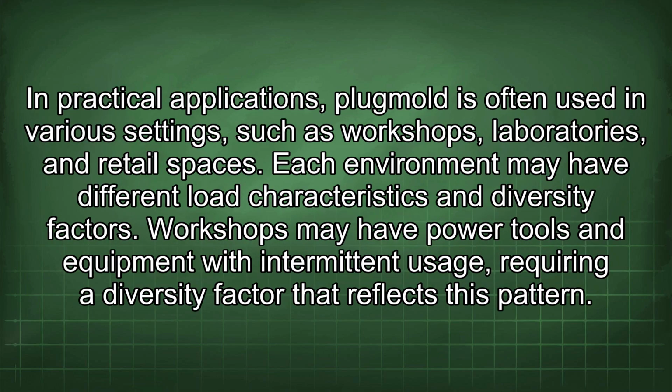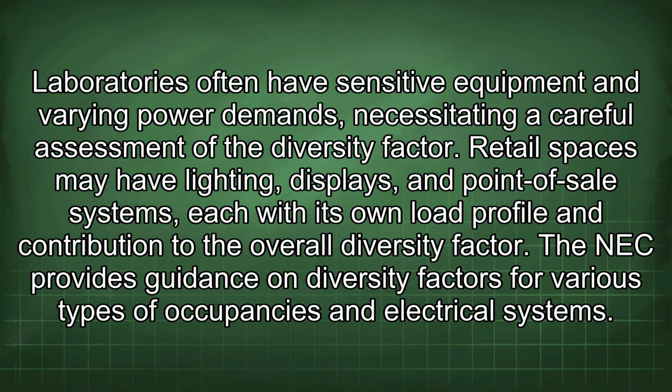In practical applications, Plugmold is often used in various settings, such as workshops, laboratories, and retail spaces. Each environment may have different load characteristics and diversity factors. Workshops may have power tools and equipment with intermittent usage requiring a diversity factor that reflects this pattern. Laboratories often have sensitive equipment and varying power demands, necessitating a careful assessment of the diversity factor.